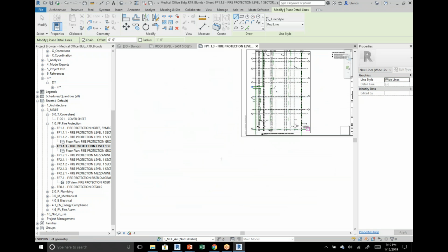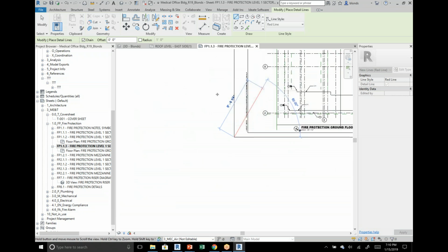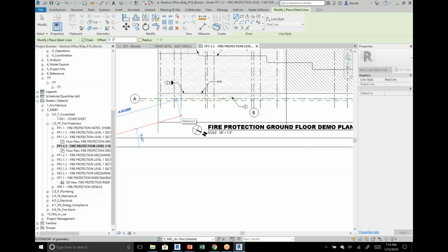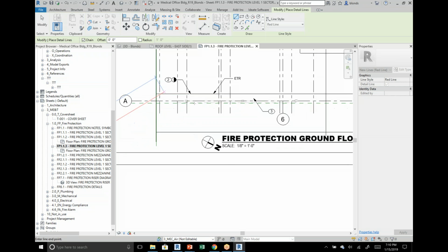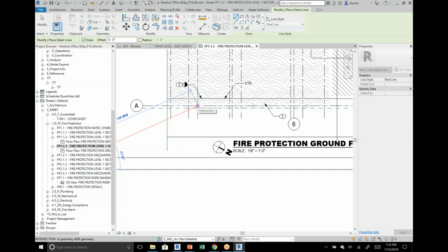So what I'll then do is I'll literally just take it from the corner of my sheet, assuming that that is going to be a constant steady point, and kind of treat that as a 0, 0. And I found that past Revit, let's say 16 or 17, in addition to being able to grab the edge of the view itself, you can actually grab into the view. So you can either grab your grid line if you think that's going to be more consistent, or the corner of your view, your choice, your preference, or why not both?